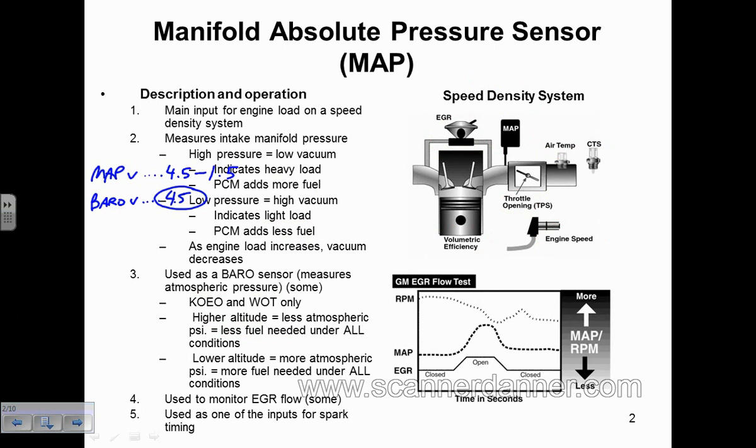Because what are you doing for your car? You're allowing that barometric pressure reading to update, and the computer can more accurately and precisely control the fuel going into that engine. If that wasn't done, what would happen? The higher in elevation you went, the richer it would run. You're issuing the same pulse width type commands for that load, but that air isn't there.